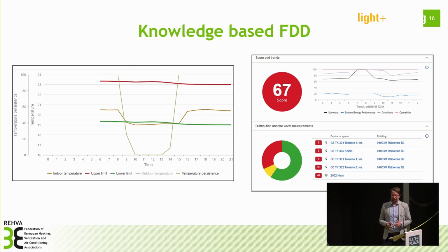The idea is, by calculating how much of the time we are between the limits, to calculate the 0 to 100 performance indicator for each room and each device, and calculate it for 1 day, 1 month, or 1 year. By that, the building expert can notice which rooms have problems with temperature, CO2, or VOC values, or which building systems have problems with energy performance. So in that size, we can also have some target limits. Let's say, for example, that heat recovery efficiency should always be more than 60%.